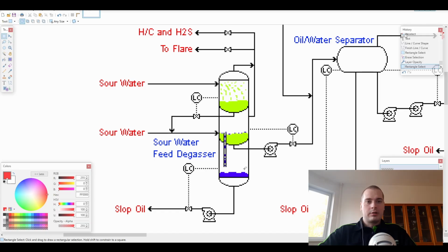So our third section is basically an oil accumulator. All this collected oil, which is a mixture of different hydrocarbons, will be pumped out to another plant where it will get recycled. And we also have a level controller here to maintain the level so it doesn't run dry.